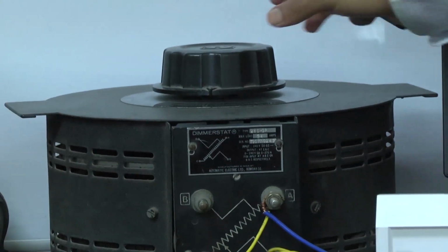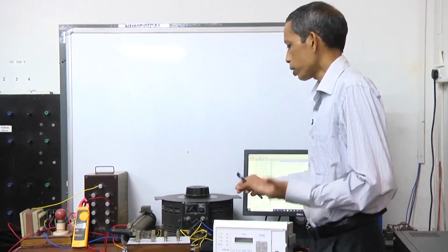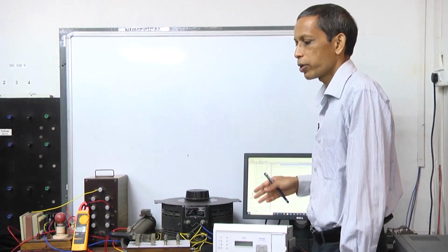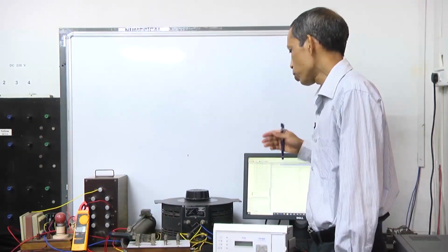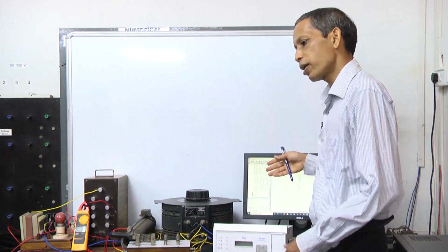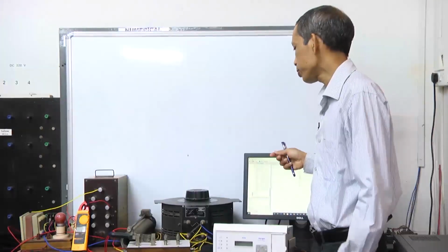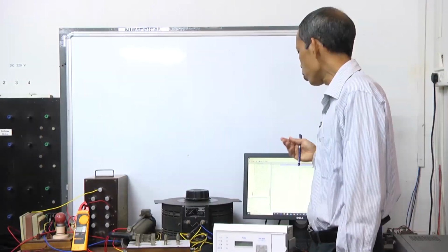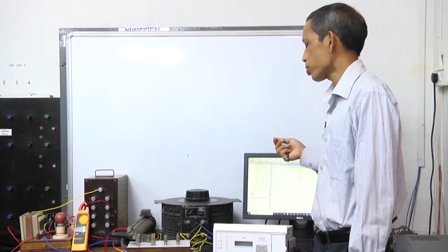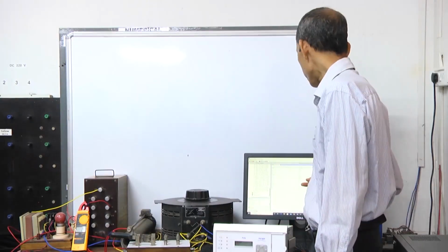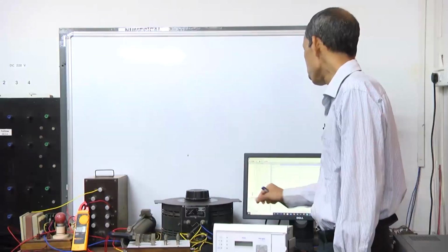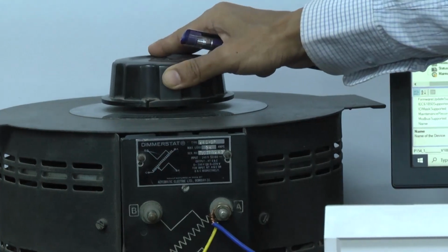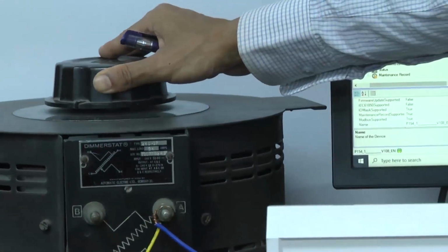So, now let us say we have, based on the PSM, the relay current upon the corresponding pickup setting. At one PSM, the time required for the trip is very high, so we will go for more than 1 PSM. Let us say we target 2 PSM for verification. So 2 ampere of current we will inject, and then see how much time the corresponding relay will take to go for the trip decision.